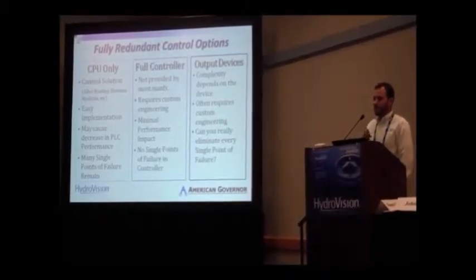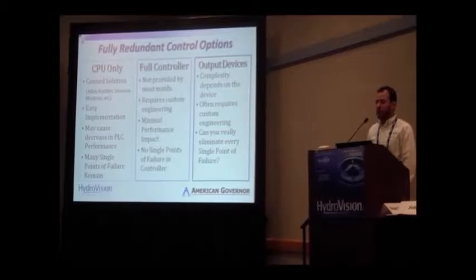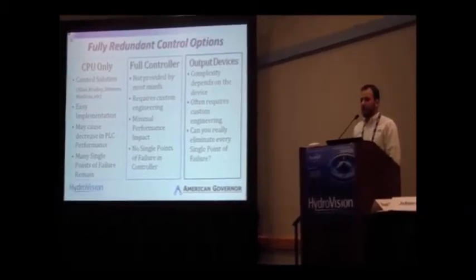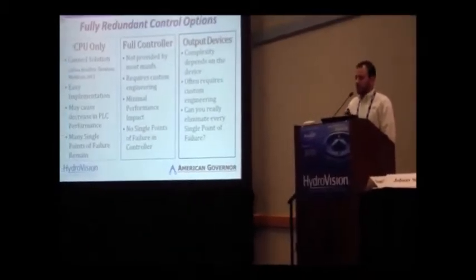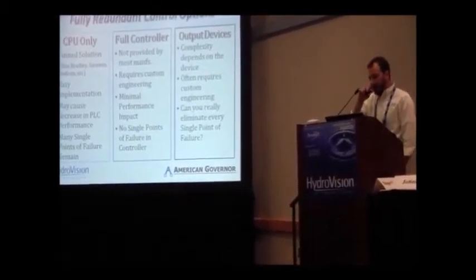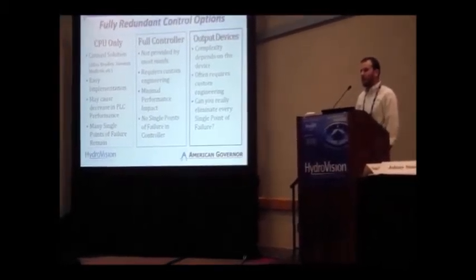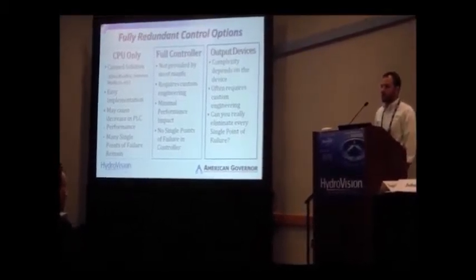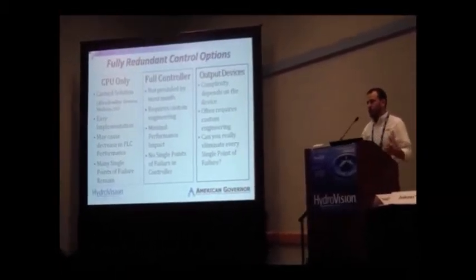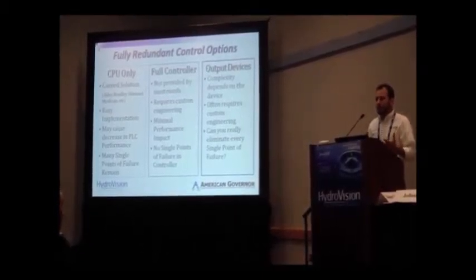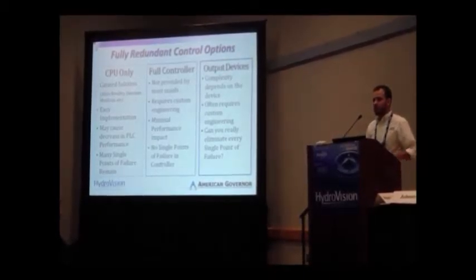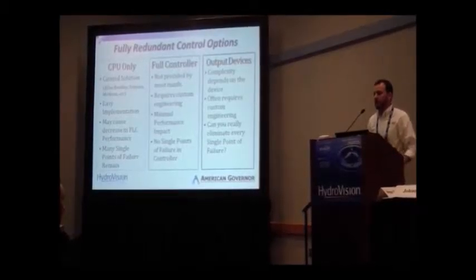So the next step will be, let's have redundant I/O across the board. And usually you'll see this in 2 fully redundant controllers running the exact same set of hardware, running parallel programs that are operating in sync. Now these often do require custom engineering, but because of that, they can be optimized and configured for your arrangement. So your performance impact is minimal. It's going to be seamless to your normal operation. And in your controller, you'll now have no single point of failure. Any controller component can fail and the unit will keep running. You'll lose some robustness because you've gone to your backup, but you can now take an outage at your convenience.